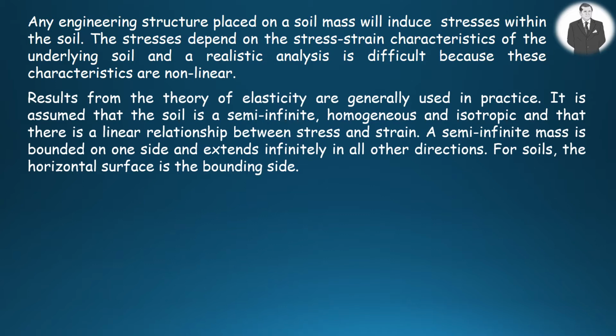It is presumed that the soil is semi-infinite, homogeneous, and isotropic, and that there is a linear relationship between stress and strain. A semi-infinite mass is bound on one side and extends infinitely in all other directions. For soils, the horizontal surface is the bounding side.